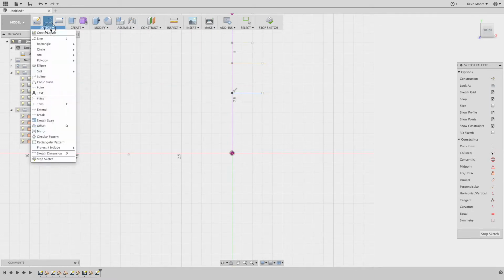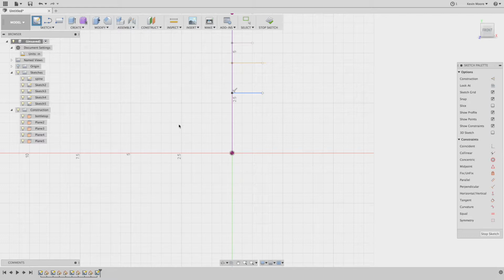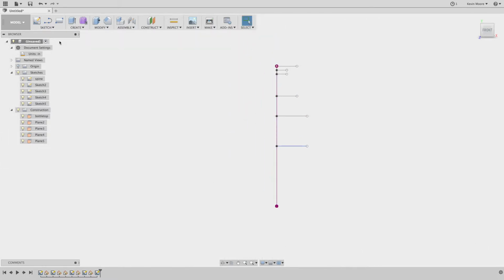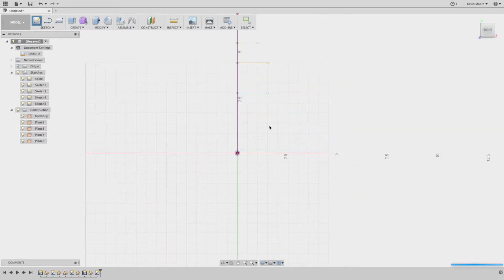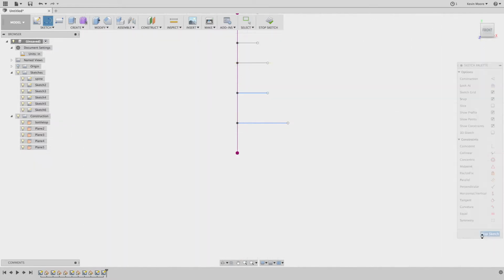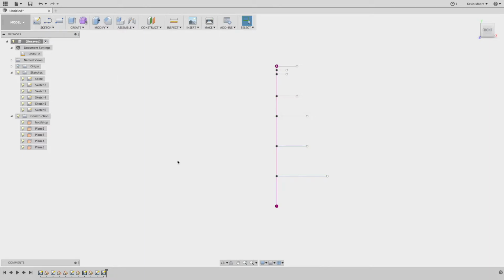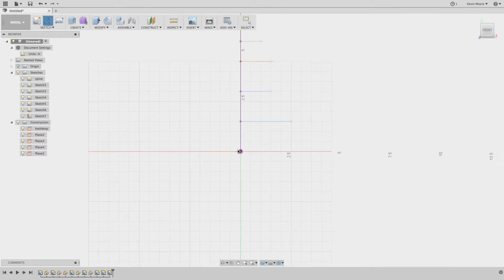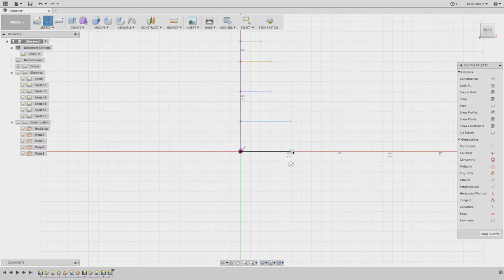So let me do sketch, create sketch, sketch, create sketch. Stop sketch. Okay. Sketch, create sketch. Click. And that just shows you if something's not going right, you just click on stop sketch over here. And then I can hit L for line, and I'm going to do one here, and then click my check to get out, stop sketch, and then if I go line, click, and my base one that I'm just going to put right there.